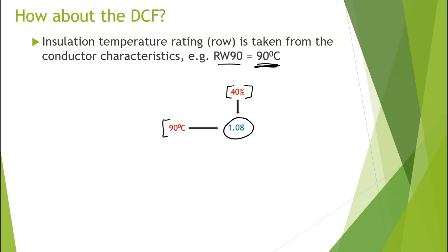This can now be used to modify our base distance in addition to the voltage multiplier and the voltage drop multiplier. And so ultimately, what we should end up with from our example thus far is a scenario whereby we got 15.5 meters out of table D3.